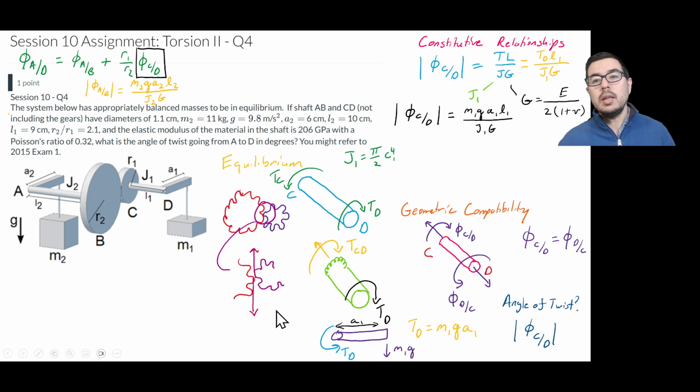So these forces are equal and opposite to each other. So we have local equilibrium. And this is a very important point when you're dealing with gears, that we think of an equilibrium of force where they interface, not of an equilibrium of torque between the two. And yes, we have situations where you have equilibrium of torque when the torque's applied on a uniaxial member, as you see here with the shaft, but this is not that case. How do I rationalize that?